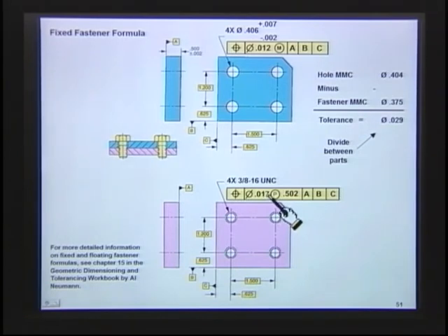As the hole gets larger, what are we really doing? We're positioning the pitch diameter. The pitch does get larger and smaller, but probably on this size screw it's probably only 1,000th or so. So again, it's the centering effect of the screw. It's probably regardless of feature size. So 17 would be all you would get. But you noticed up here, and this is the clearance hole, you could have the advantage of maximum material. And as the hole gets larger here by a total of 9, that 9 you could have up to 21.